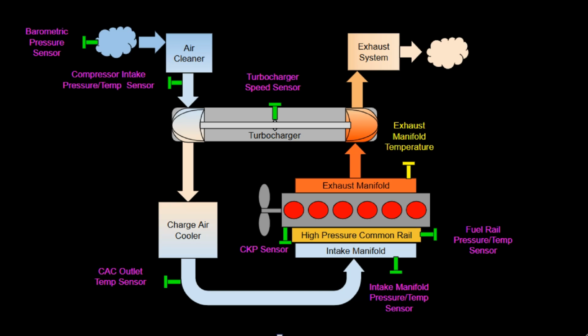Monitoring the exhaust temperature is important for diesel engine reliability since high exhaust temperature can damage the turbocharger turbine and other exhaust system components. And most ECMs will throw a DTC and probably a derate if the exhaust temperature is determined to be too high.